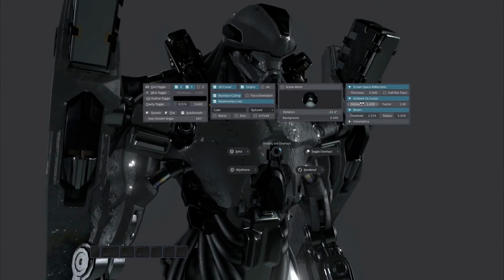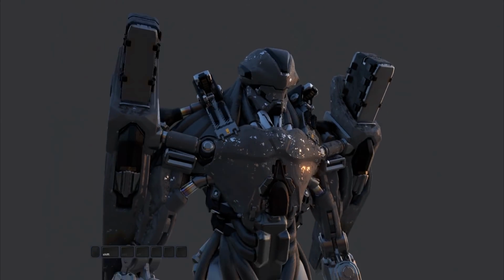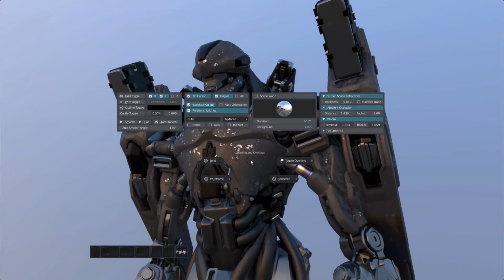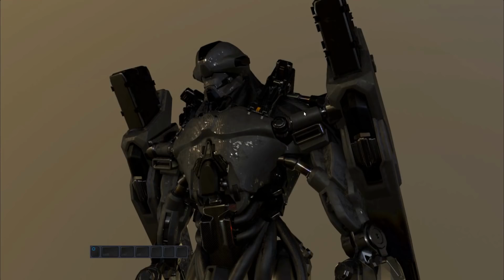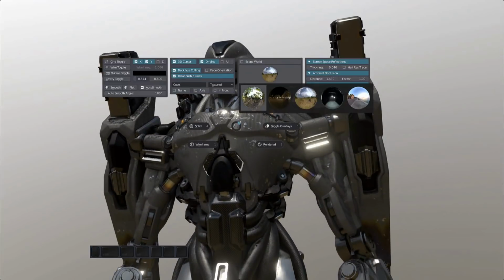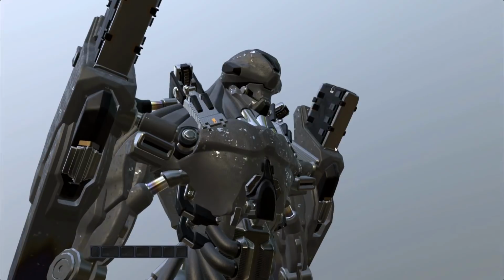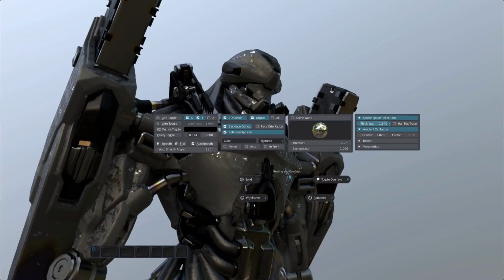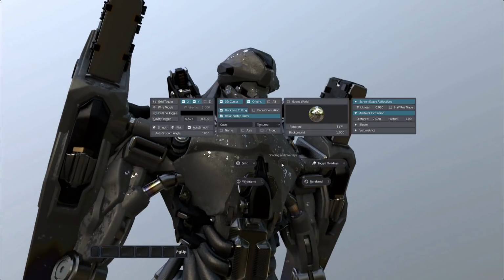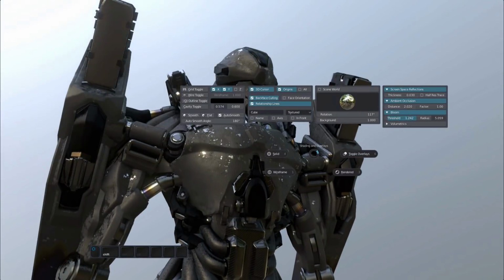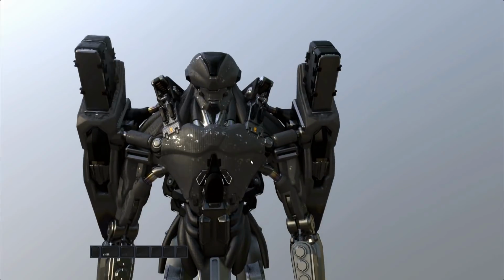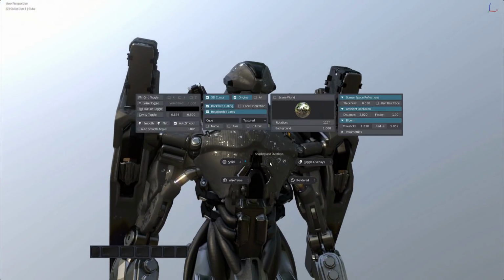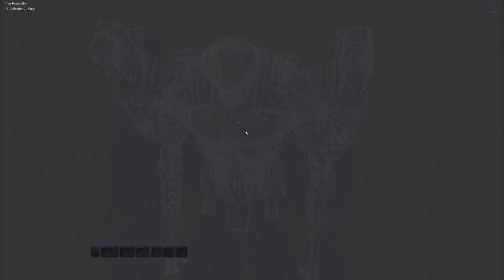Instead of matcaps, you can choose environment maps in Look Dev mode. You can also access ambient occlusion, screen space reflections and bloom from here, even if the scene renderer is set to Cycles. Wireframe shading and rendered shading can be accessed as well.